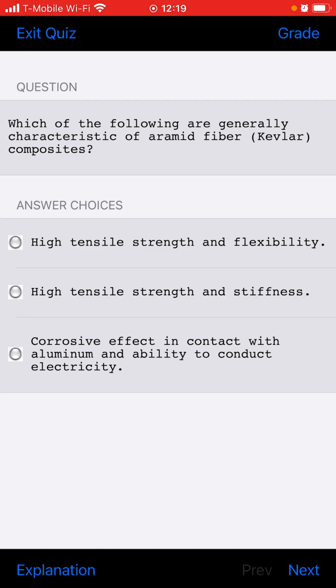When riveting dissimilar metals together, what precaution must be taken to prevent electrolytic action? Place a protective separator between areas of potential electrical differences.